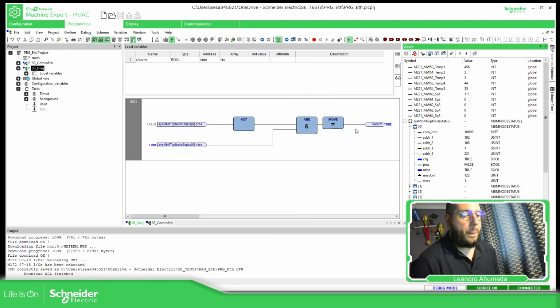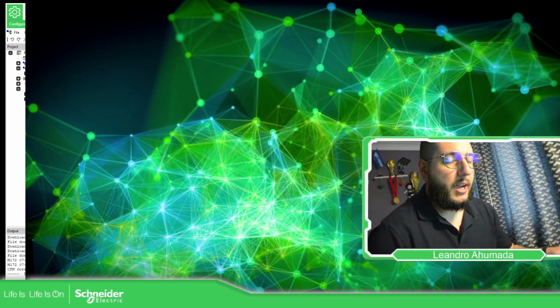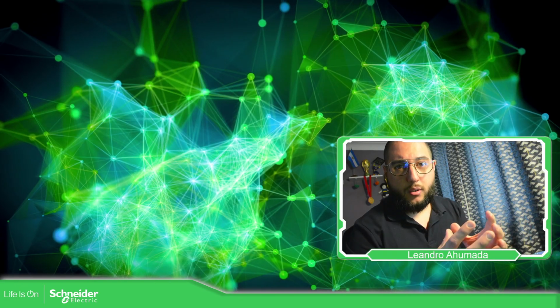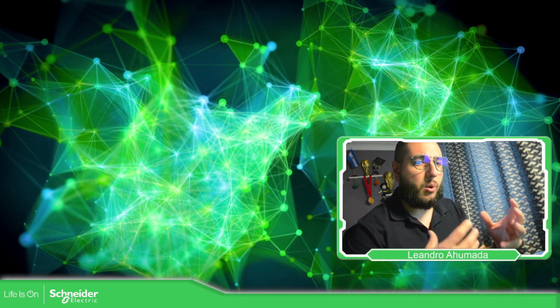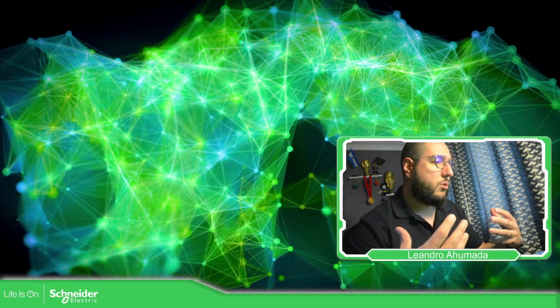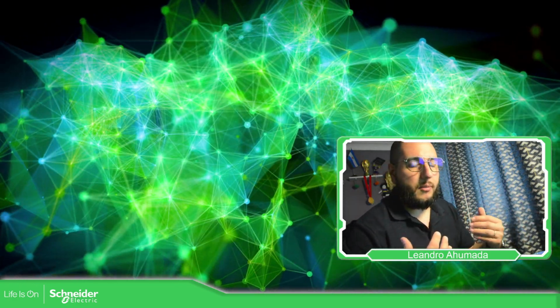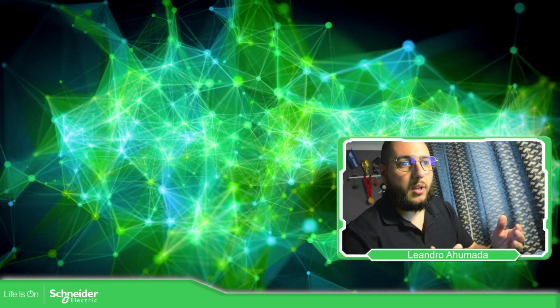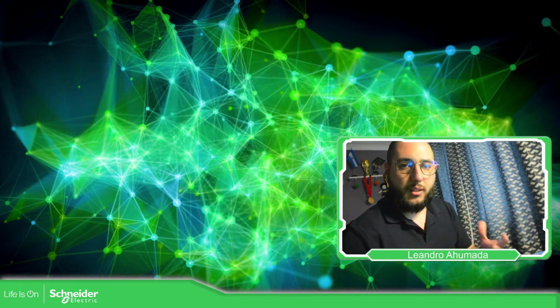Okay, so this is how you can create your own Modbus device to easily reuse and have all the registers already in there, ready to find. So in the next project, you can import it or read from the catalog that device instead of copy and pasting and create a new one. So you have more versatility in that case.